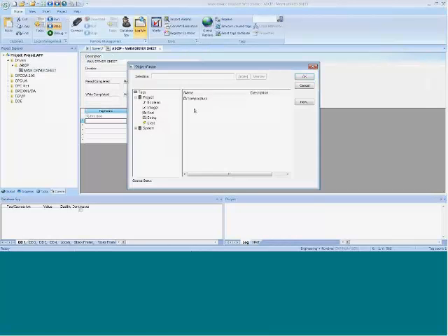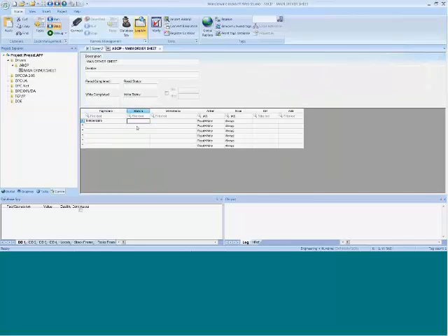Now I could tie that temperature tag through an IP address, that's what the station field is for, to the I/O address in the PLC. If it happens to be a ControlLogix PLC, that could be the tag name, or if you have it mapped to the old PLC 5 style addressing, it could be like N7:0. It depends on what type of PLC and driver you're using. But the general idea is this is the glue that ties the InduSoft tag name to the PLC I/O address.